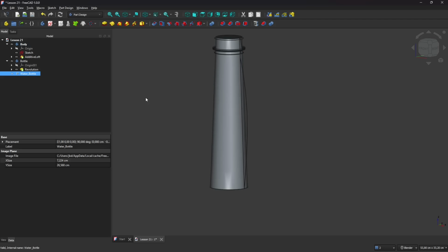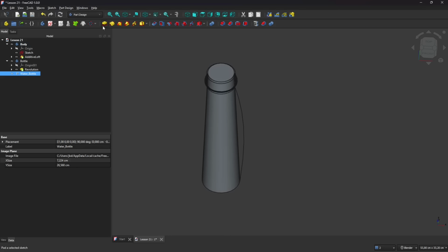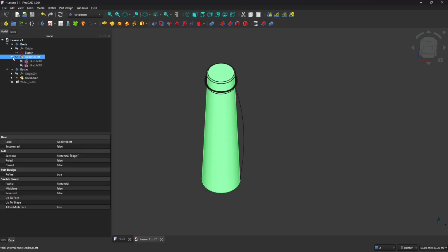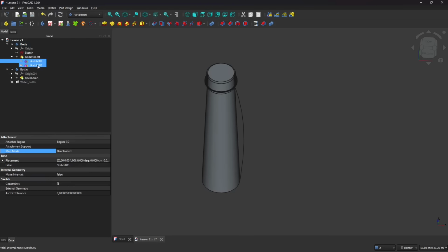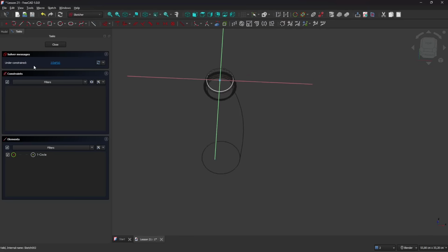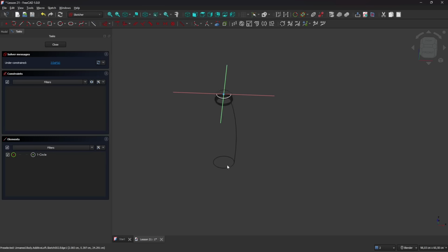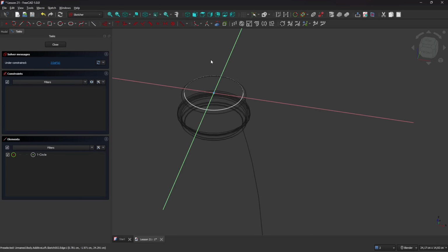So some objects are not symmetrical and they are not developed around a circle like the revolve or this type of loft, and they are more complex. This is because of the way they are constructed, the way they have their profiles. So if I go back in this, this is the bottom sketch and this is the top sketch. If I go in the top sketch, first of all, you see they are positioned into different planes, work planes, or references, work reference planes.